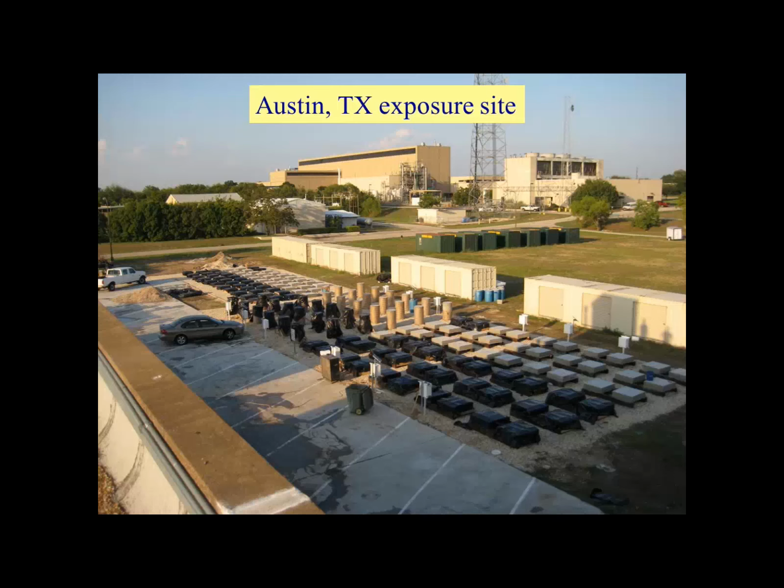For instance, I think we estimated that 1 to 2 layers of FRP wrap would be enough external confinement, and we did a study where we did 1, 2, and 4. Our thinking is that the least confined one should actually fail, which we would then observe, and the one that has the most layers of FRP wrap should provide enough external restraint to basically take care of the ASR.